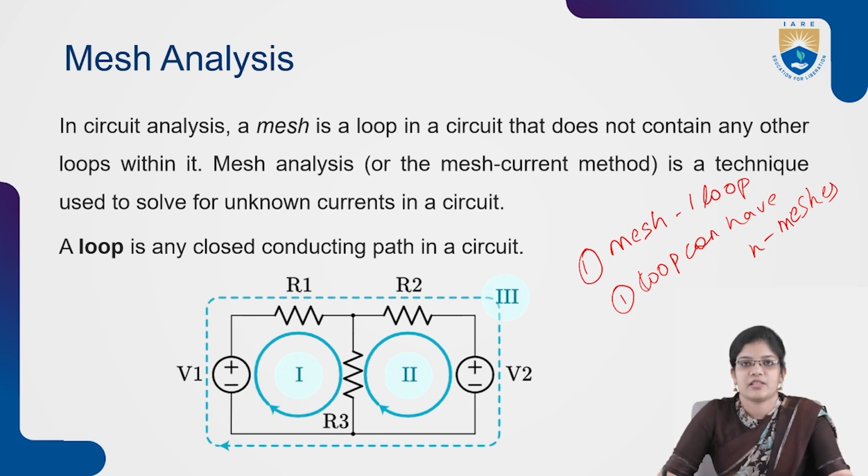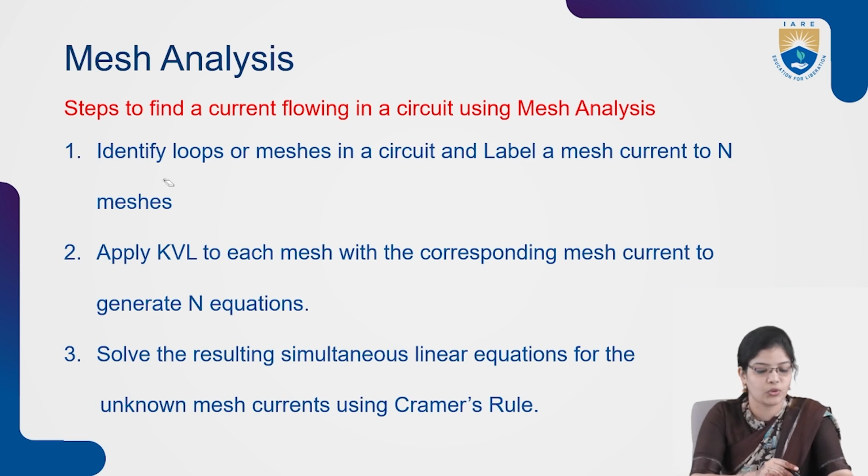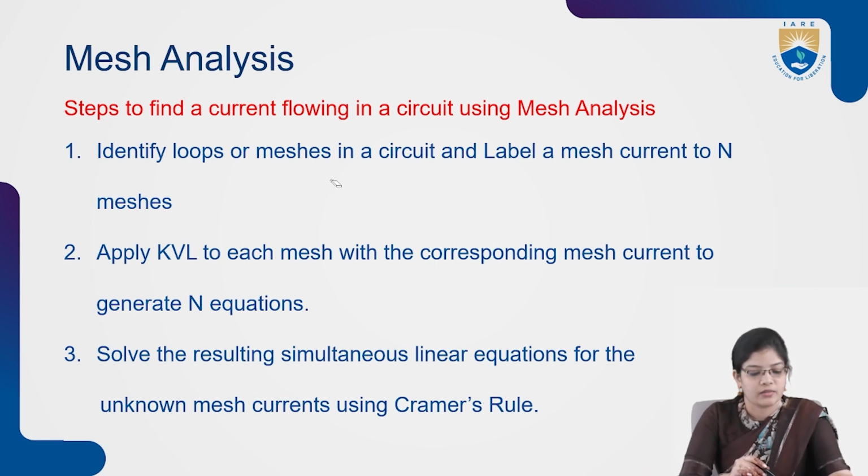In the previous lecture, we also discussed the steps to solve mesh analysis, and we even solved two problems regarding mesh analysis. Once again, I'll recall the steps. First step, we have to identify loops or meshes in a circuit and label mesh currents to n meshes.